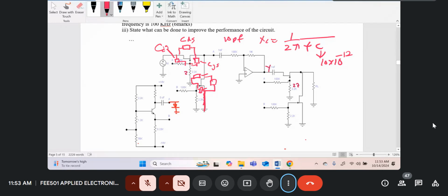And this is the switching frequency. Since the voltage that we want to switch is a very slow varying voltage, I told you the period of the signal could be maybe half a day. So you don't have to switch at a very high frequency. Because from Shannon's theorem, to recover all the information inside a sampled signal, you only have to sample it theoretically at twice the frequency.